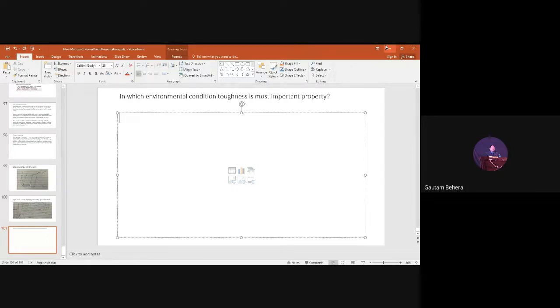Yield strength means the stresses or the load on the brace should not be above the yield strength. But during the application, the brace has bent now. That means some yielding has happened. So that is a failure. But if the brace separates into two pieces completely, then it is a fracture.